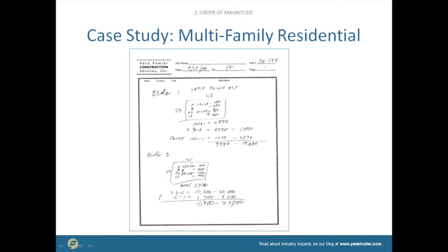So I used an aerial image, and I figured out that this building type was this size, and I think that's 2,840 square feet of siding on that building, and the siding was going to range from $3 to $6 a foot, and paint was going to be 50 cents to $1, and so it was somewhere between 10 and 20 grand to side that building, depending on the details. And this building type, building 2, was going to be somewhere between 12 and 24,000, right?